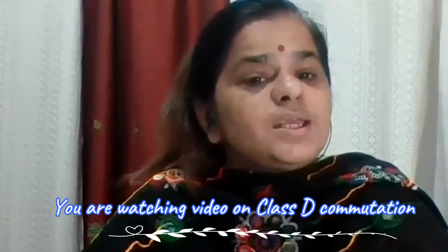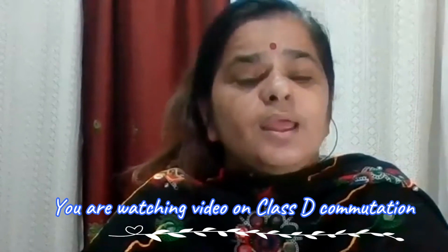As the name indicates, in this kind of commutation, we artificially create a voltage and apply it across the SCR which is already conducting, in the reverse bias condition for a sufficient duration, and then the SCR will be off. Since the SCR is off because of the reverse applied voltage, its name is voltage commutation.